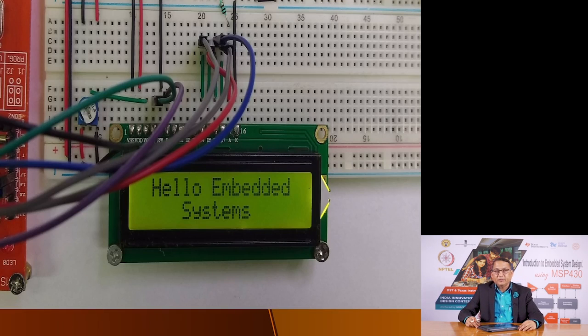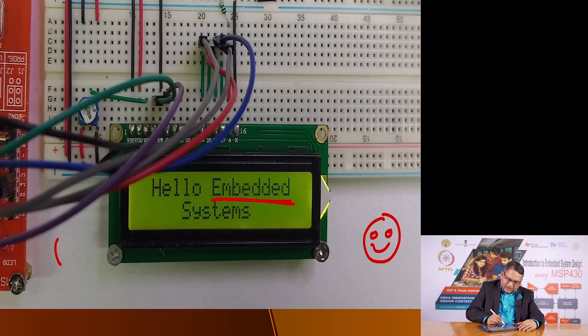Now the LCD is capable of creating custom characters also. These are all built-in ASCII characters that it is able to print. But what if you wanted to print a smiley, something like this, or a heart, something like this? It is possible to print the heart like this by creating a pixel character and storing this information in the RAM that the LCD has,